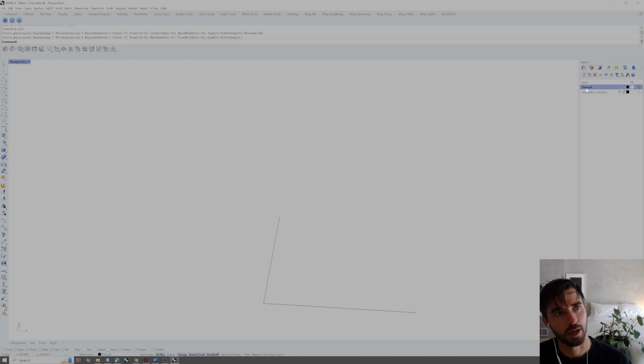The check mark and bold indicates whatever the current layer is. So if we were to make an object right now, it would by default be applied on the default layer. If we wanted it to by default be applied to the geometry samples layer, we would just need to double click on that layer. Now anything we make will be applied inside of that geometry samples layer. We can nest layers to keep our files nice and organized so that we can toggle or select relative to the layer structure and not just based on whatever objects we're placing in the scene.